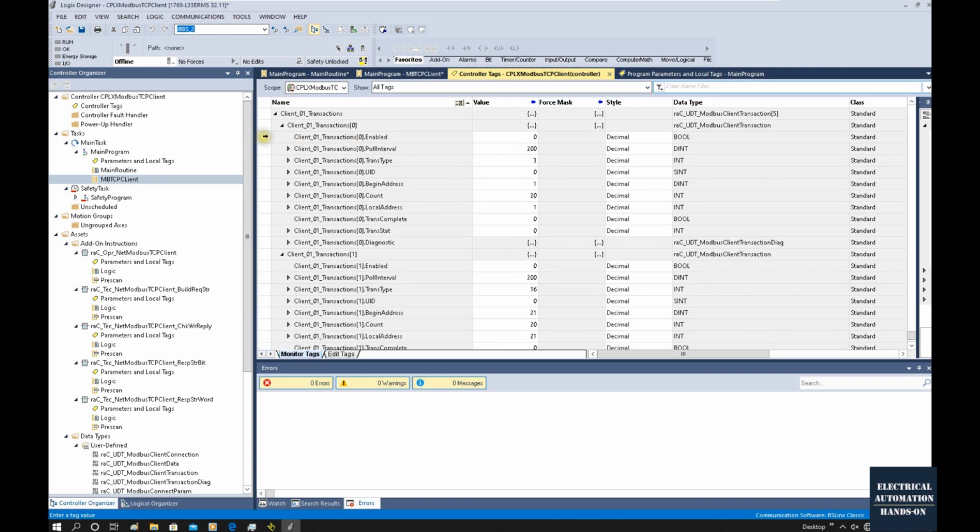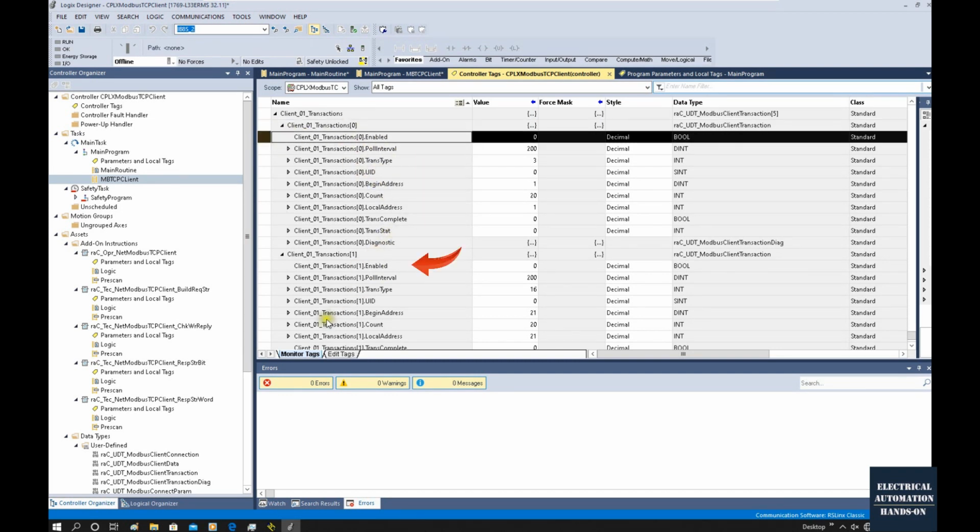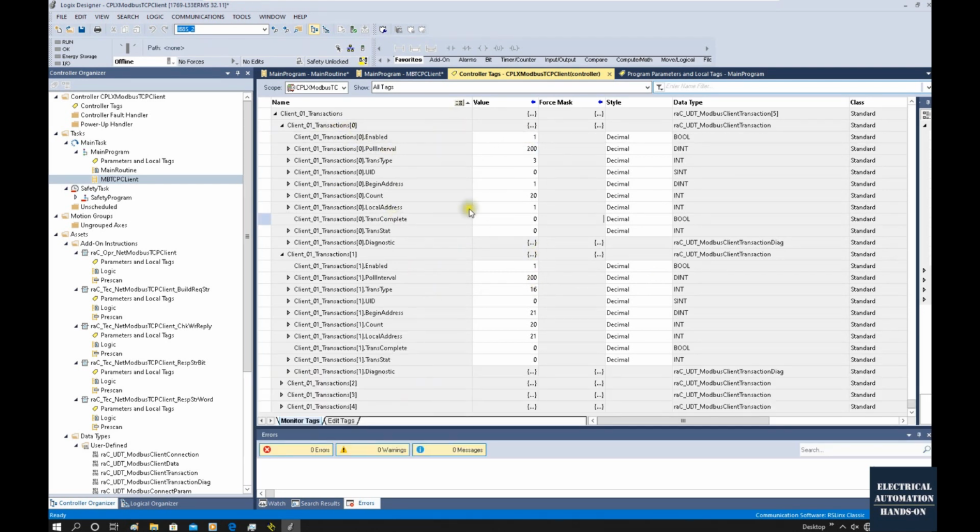And also here, the enable. This enable will enable the different function codes, the commands. Personally, I highly recommend those enables cannot be turned on at the same time. You need to use time slices to turn them on individually, one by one. They cannot turn on at the same time. Otherwise, you will see the time overlap output turn on from this function block. But for testing purposes, we can turn it on. I will show how this time overlap turns on. Okay, now we have finished all the important settings here, and we can download this program and try this connection.